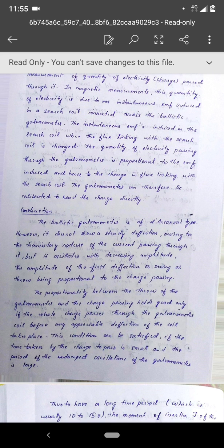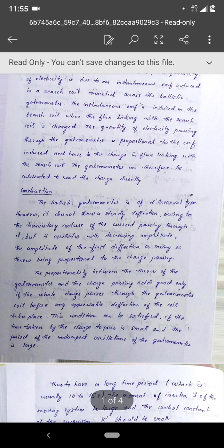Whatever the connections are, they are made by very loose helices, so that they don't impart any tension at any point. And the damping torque is avoided because the moving coil is wound over an air core, so that you can avoid the damping effect.